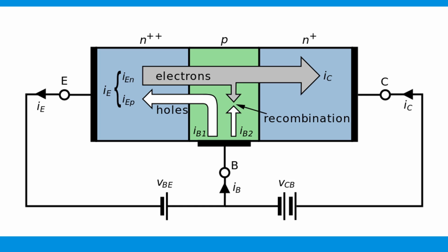By design, most of the bipolar junction transistor's collector current is due to the flow of charge carriers, electrons or holes, injected from a high concentration emitter into the base, where they are minority carriers that diffuse toward the collector, and so bipolar junction transistors are classified as minority carrier devices.